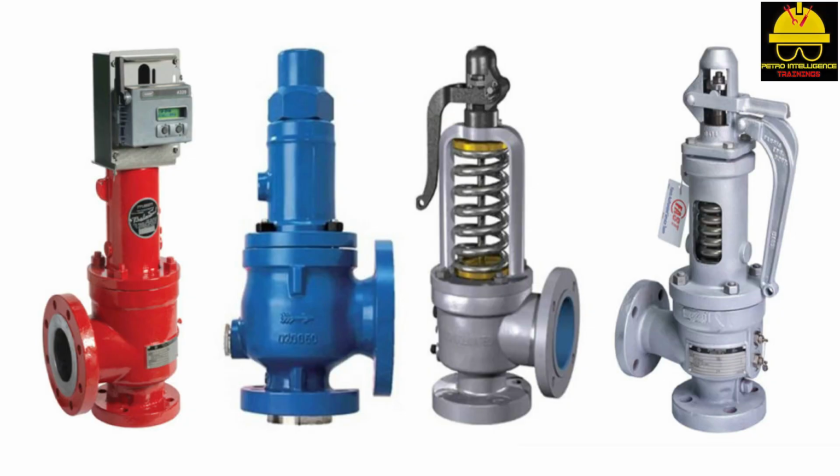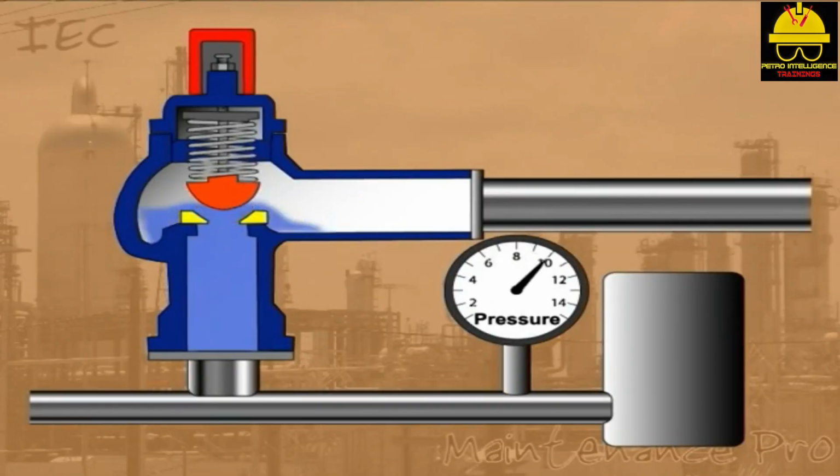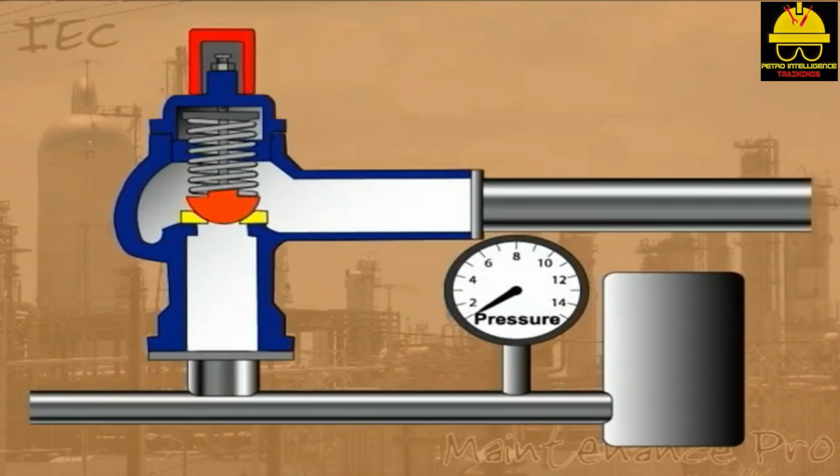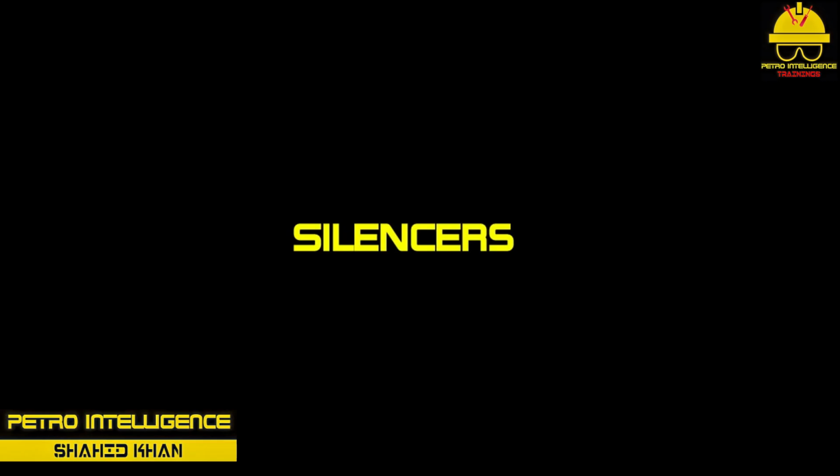Safety valves. Safety valves and pressure relief valves are used to relieve excess pressure that could damage operating equipment and hurt operating personnel. These valves are sized to handle specific flow rates and should not be replaced without ensuring that the replacement valves meet engineering specifications. Some safety valves automatically reset, other types must be removed and mechanically reset.